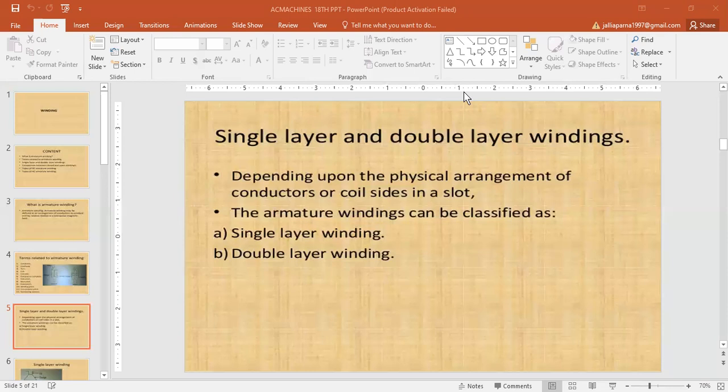Two layer winding. In this type of winding, the coil sides are arranged in two layers. Usually, one side of every coil lies in the upper half of one slot and the other side lies in the lower half of some other slot at a distance of approximately one pole pitch away. The transfer of the coil from one slot to another is usually made in a radial plane by means of a peculiar bend or twist at the back end.